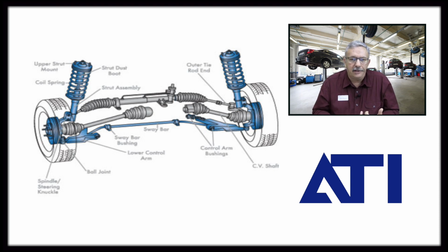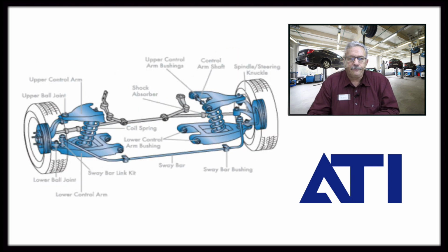So what's important? We've got to look at the strut tube. We've got to make sure that the springs are able to do their rise and fall with the suspension. We've got to make sure that all the mounting locations are where they're supposed to be, because if they're not, typically a part will bend when those parts move. So we've got to do the visual inspections.